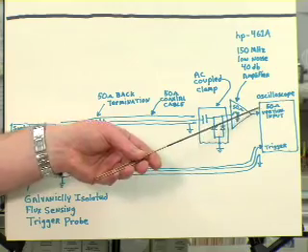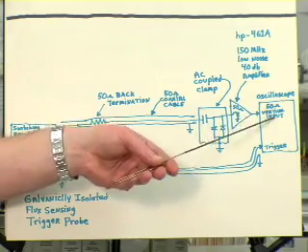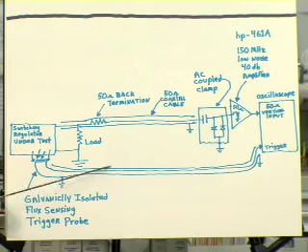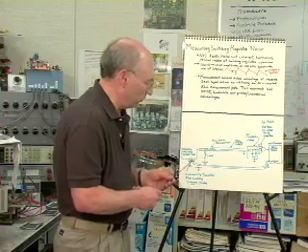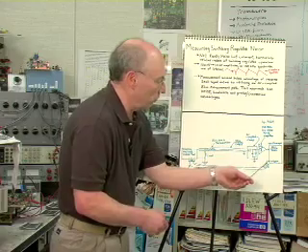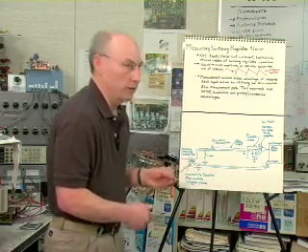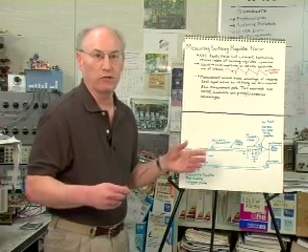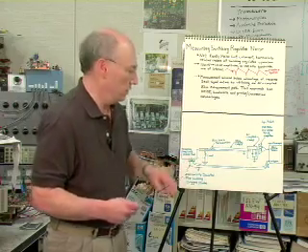The preamp output feeds a 50 ohm scope, which is triggered by a flux sensing probe located above the magnetics of the switching regulator. The reason I do this is to break up any potential ground loop path between the scope and the regulator board, so there's no galvanic connection in the trigger connection.